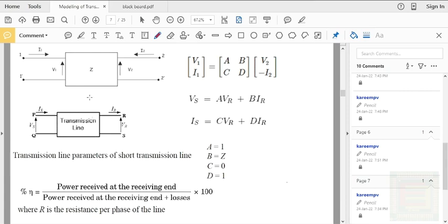And if you consider the transmission parameters, you might have studied this in network analysis. In case of a two-port network, you have two sets of parameters. If you consider this two-port network, you have four quantities I1, V1, with these directions as indicated. I1 will be flowing into the network, and this is the voltage across the first port. And here you can see that I2 will be flowing into the network. As far as the transmission line is concerned, IS, the sending end current, will be flowing into the network, and IR will be flowing out of the network.